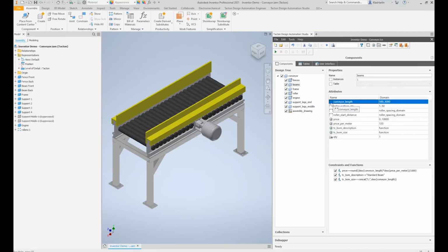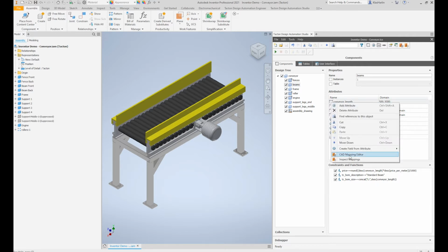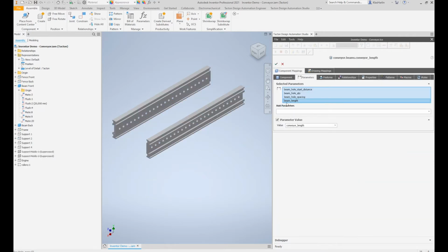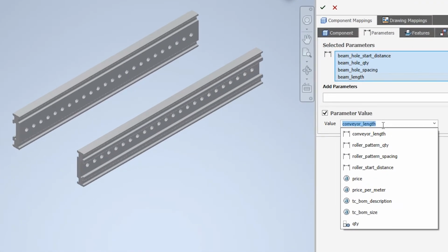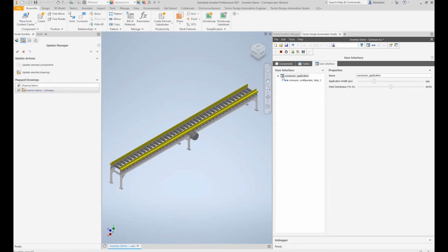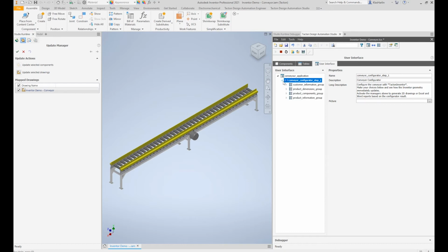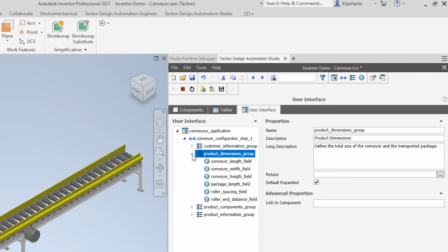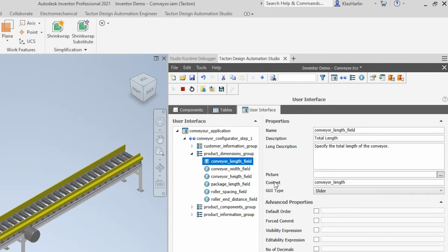Next, the configuration constraints and parameters are connected to the corresponding CAD parts in your assembly, driving the design, sizing, and measurements of those. This means that the design is automatically adjusting to the configuration logic. And since the configuration logic always ensures that the technical solution is valid and correct, so will the CAD design be. Based on the configuration logic, you then design the requirements questions in the configuration interface, using, for instance, range sliders, drop-downs, radio buttons, or input fields.